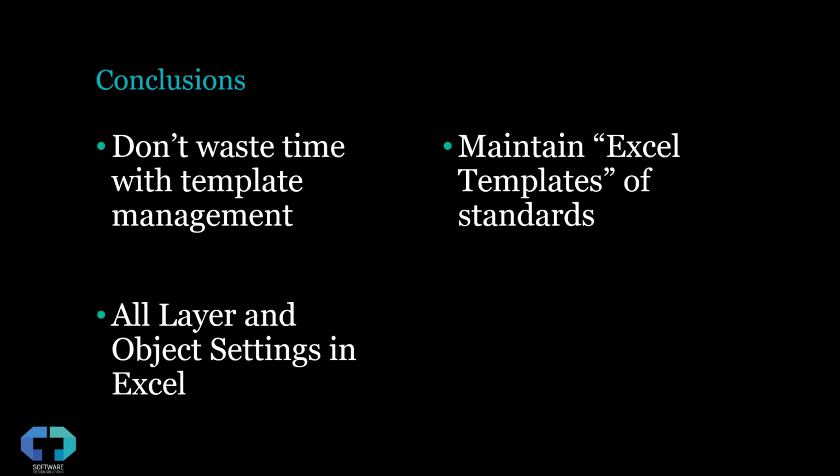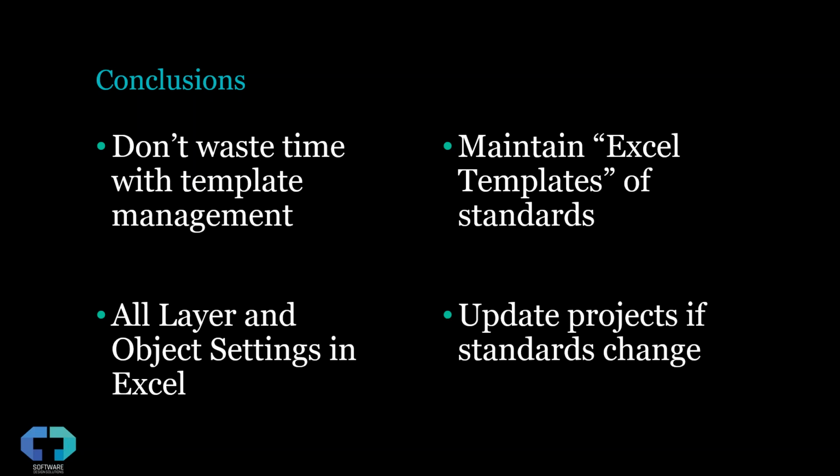If there was a big overhaul happening, perhaps you need to make a new template itself, you can run an export from your existing templates, make all those changes, and then push that stuff into a new template. And then, of course, if these standards need to get pushed out to existing projects, drawings that were already made months or years ago even, you can do that very easily with Layer Boss. You can also do it with Survey Template Manager, pushing out changes to your description key set and your figure prefix database in a similar way to what we had done here.